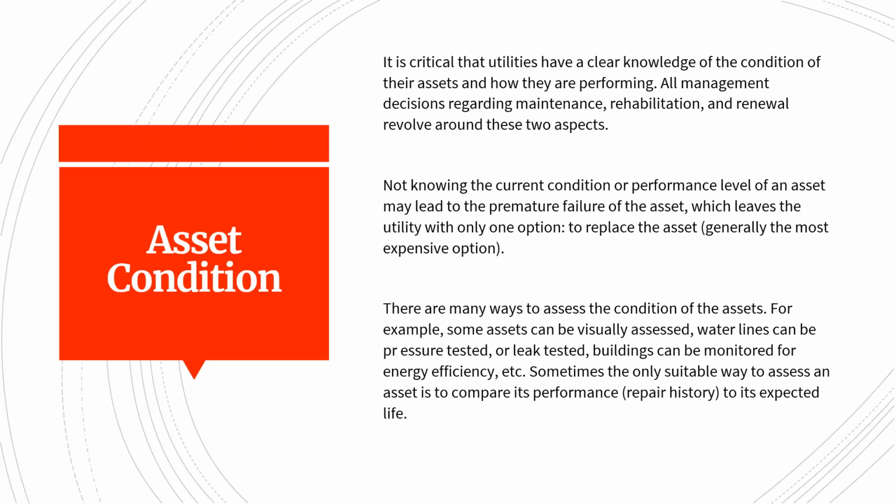There are many ways to assess the condition of the assets. For example, some assets can be visually assessed. Water lines can be pressure tested or leak tested. Buildings can be monitored for energy efficiency, etc. Sometimes the only suitable way to assess an asset is to compare its performance to its expected life.